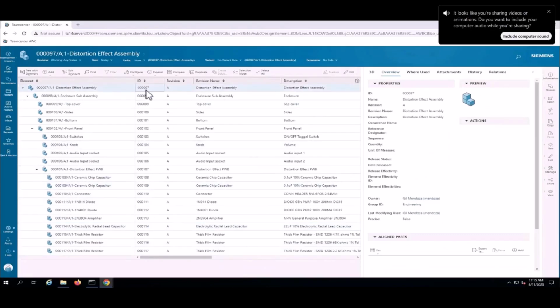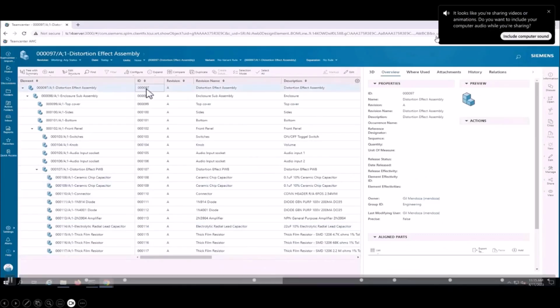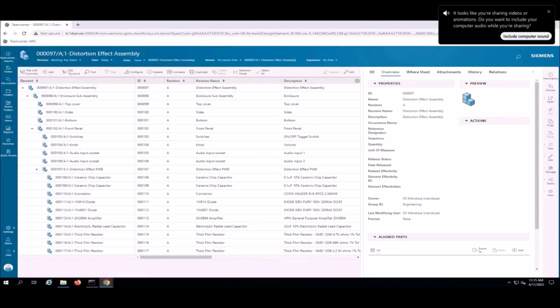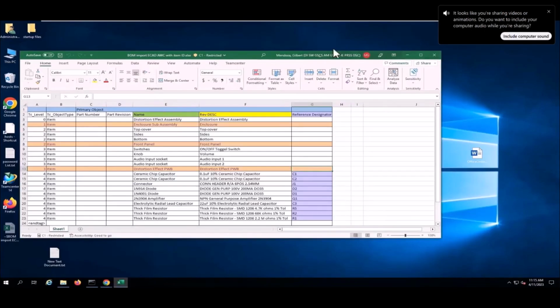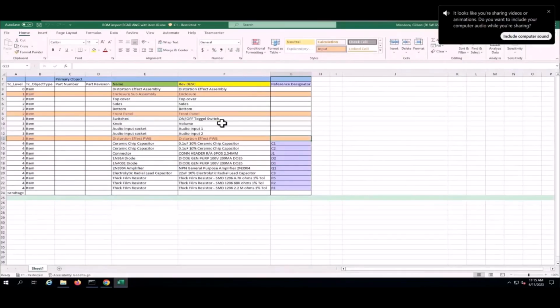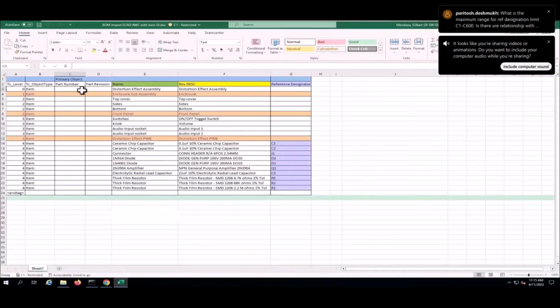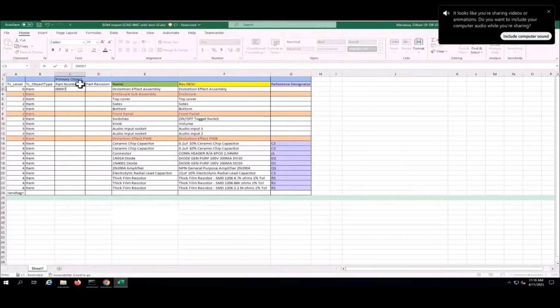It starts at 097 and it went to 117, all the way down to the bottom. So I'm going to keep that in mind, and we're going to go back out and I'm going to re-import this BOM, because of a question I see that may be one of the questions. What happens if you go in and those parts already exist? Then what happens? So I'm going to, on purpose, start the part numbering. So I'm going to go 0097. I forgot to put another 0 in there, so I'm going to add another 0.